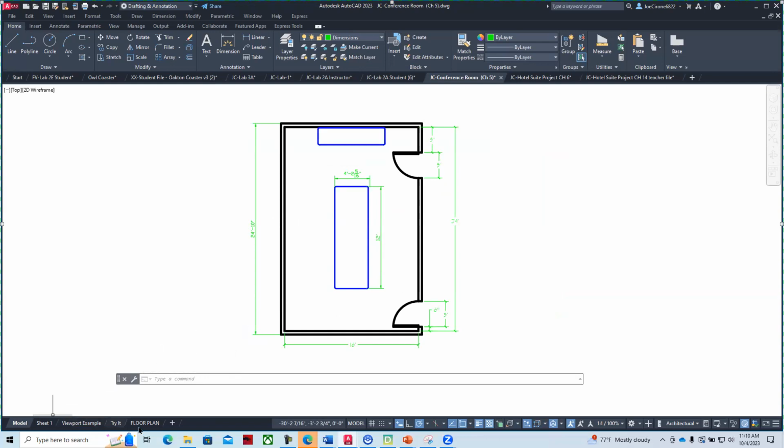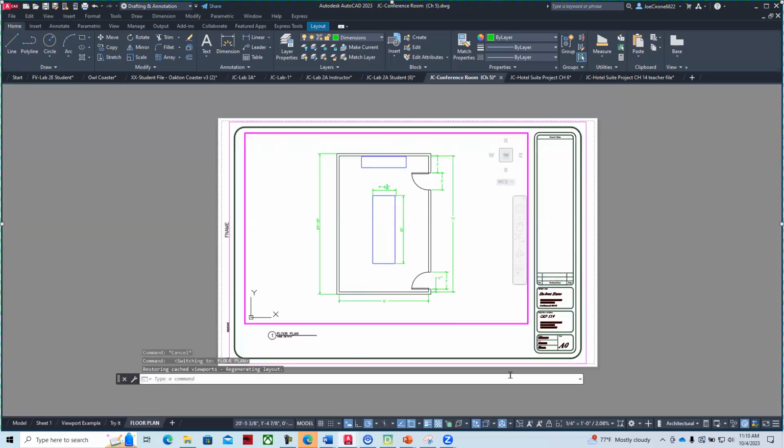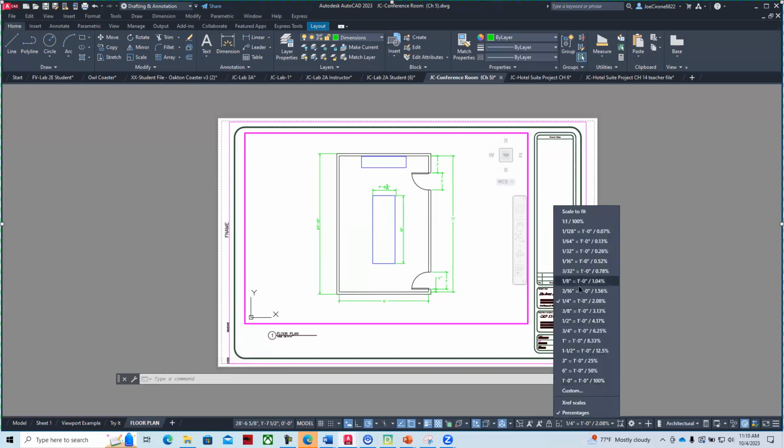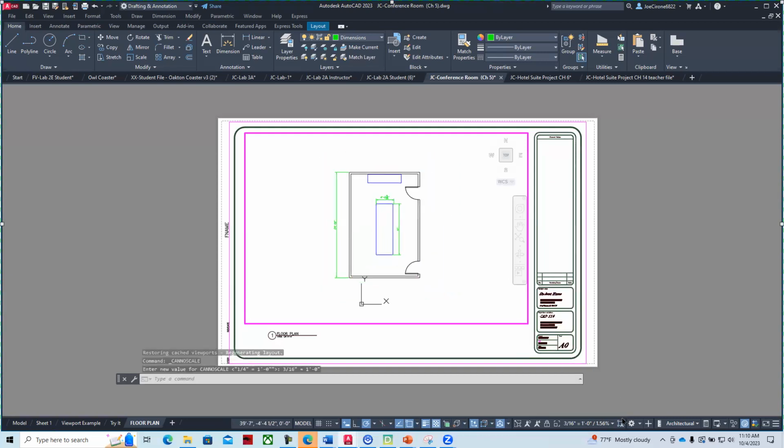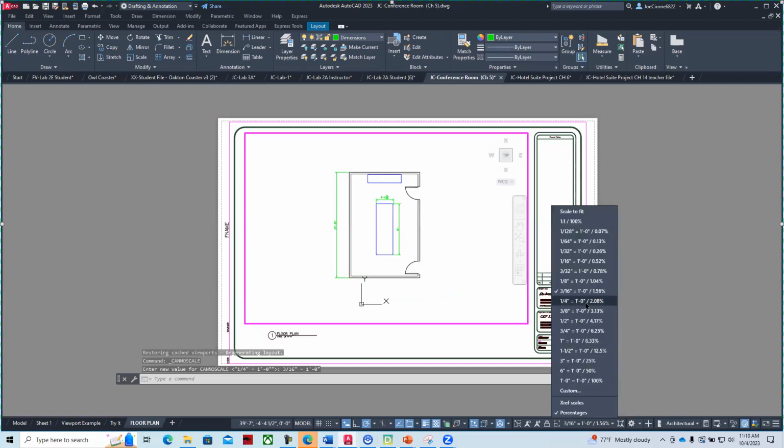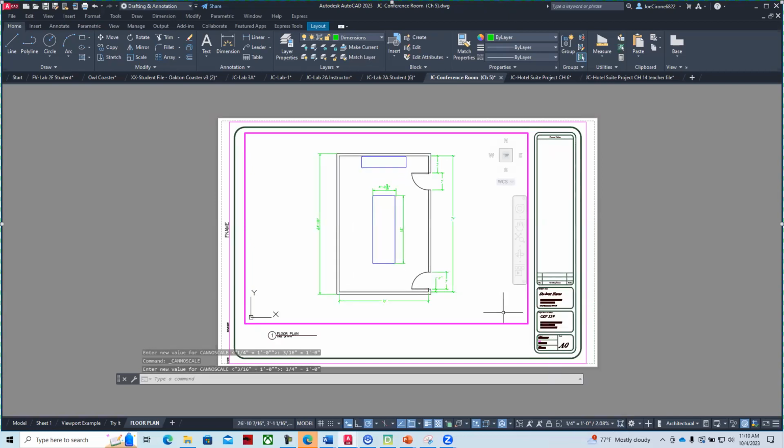And then when we put it on the floor plan, we just want it to be measurable with an architectural scale on the printed paper. And so we dial in the viewport scale. I could set it up at 3/16, 1/4 of an inch, and that's reasonable. It fits within the paper. I could shuffle it around a little bit, add some more 3D elements, and then we lock it.